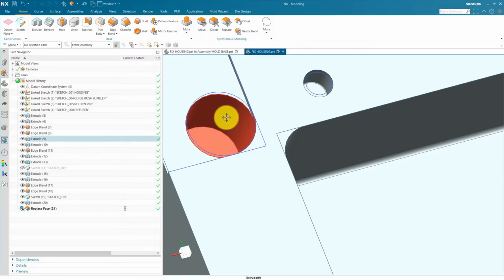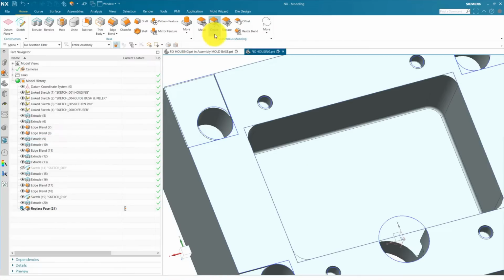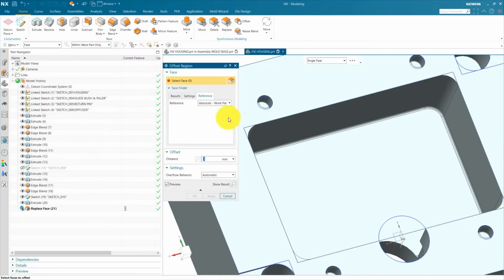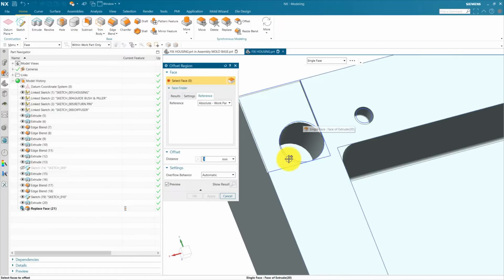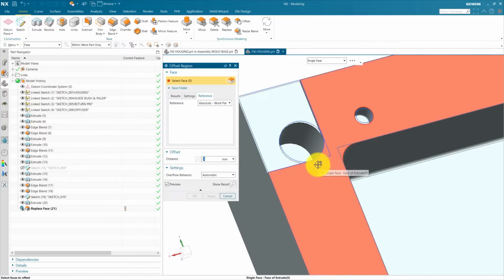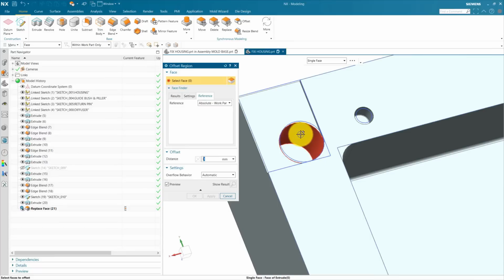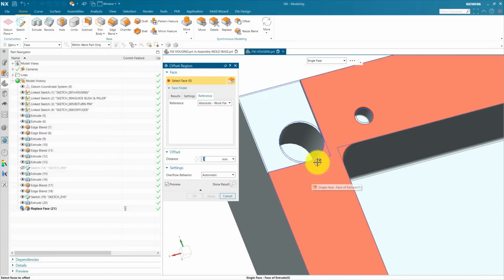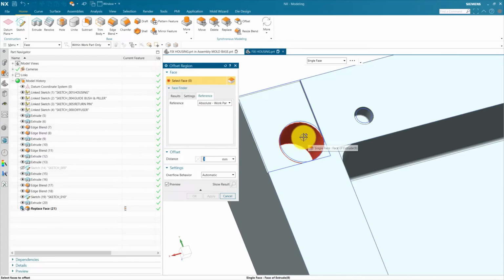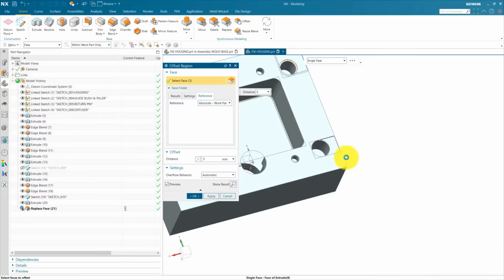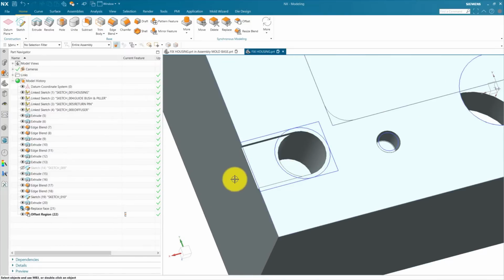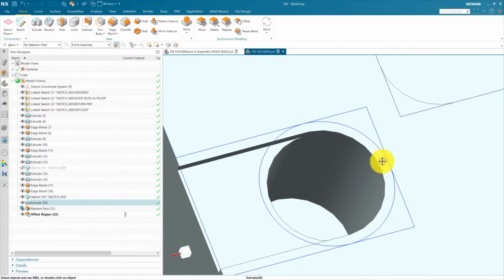Okay. Offset this hole 5 mm inside, because this circle is the size of our guide bush, which is used in the moving half. In the fixed half we use a guide pillar. The guide pillar base diameter is smaller than our guide bush base diameter. Is it okay? This is also updated.